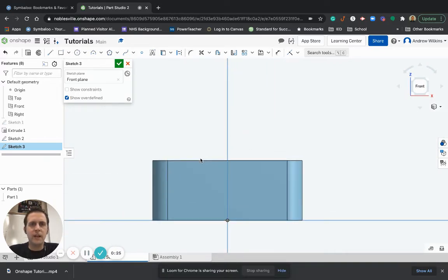The parts I'm going to make, I want to lock onto the top of this object. But in order for that to happen, I need to use that surface. So if I click on this use icon right here, and I select that line, it has now been pulled into my sketch. You can actually see there's a line there now where there wasn't before.